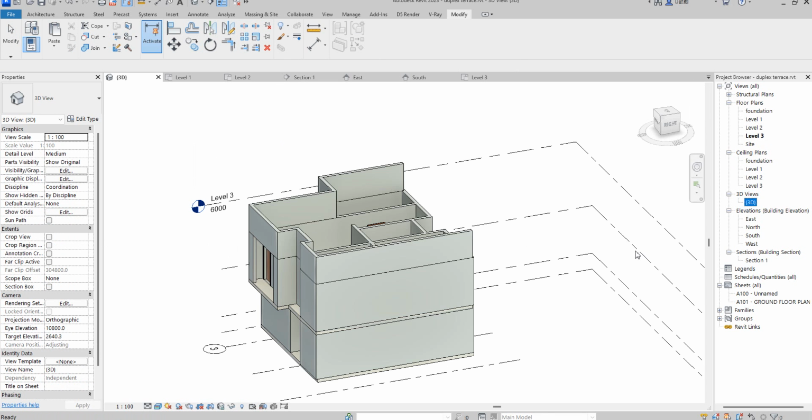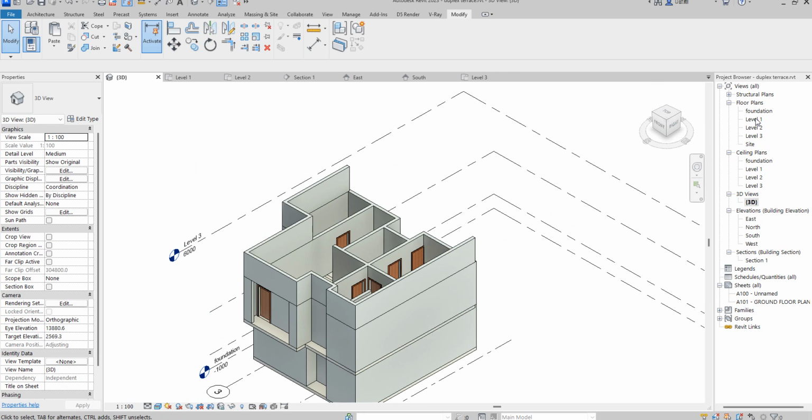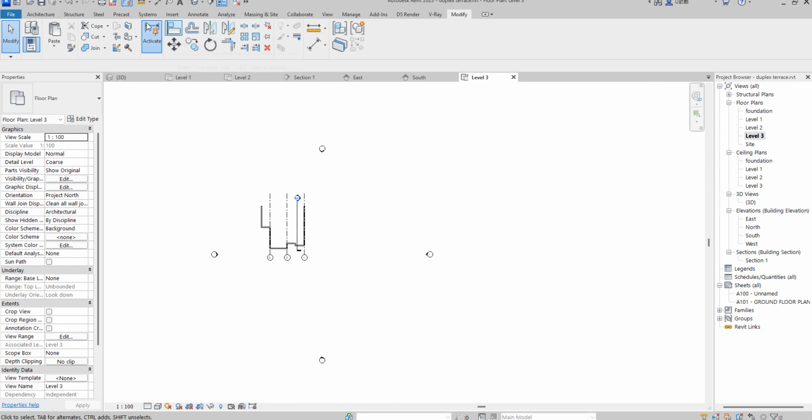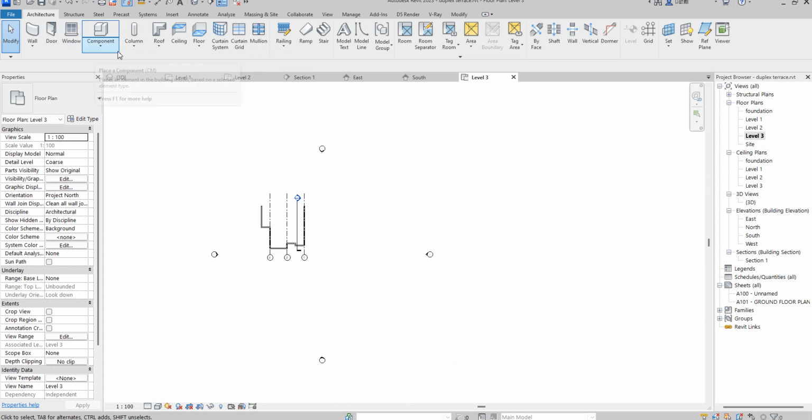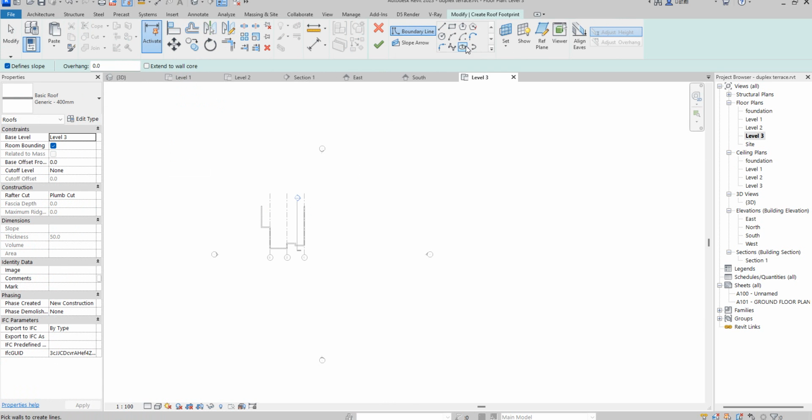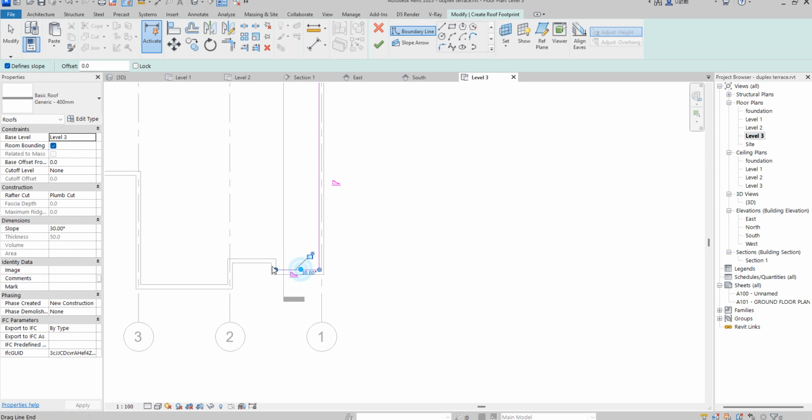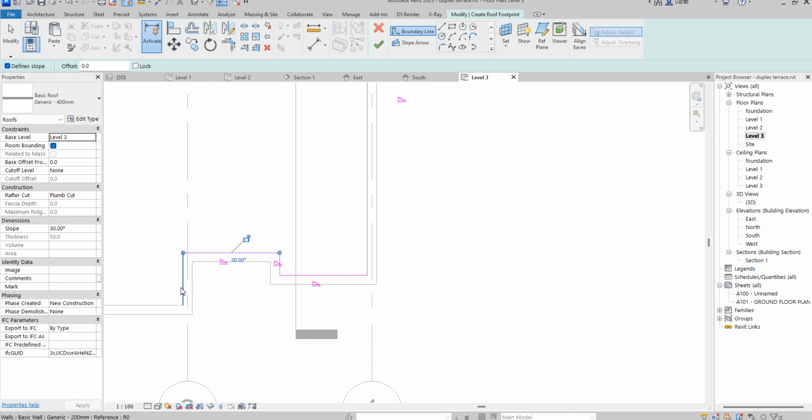So as I have it now, you go to 3D view and see. So this is how far it goes. So the next thing I need to do now is to quickly work on the roof and create it. So I'm going to say create. So this is done. Then I will select by line everything that's pertaining to what I'm doing. So you should see there are some other options that are here, but because you have not done anything, most of those things you're supposed to do are not going to be appearing. So I'm just going to make this so that the sketch is done.